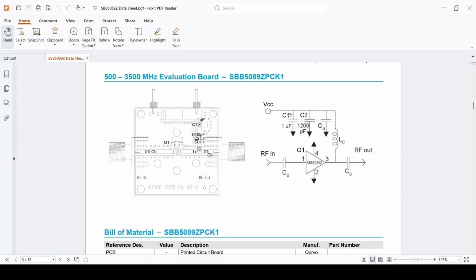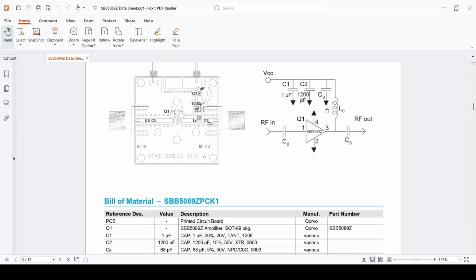We provide a high value capacitor, and we know that this high value capacitor is probably not good at high frequencies. So we add another lower value one for middle frequencies and a very small one for very high frequencies, because this, let's say, CB of 68 pico, because it's very small, its parasitics are small, so at very high frequencies, this capacitor will act more like a capacitor compared to the larger ones, right?